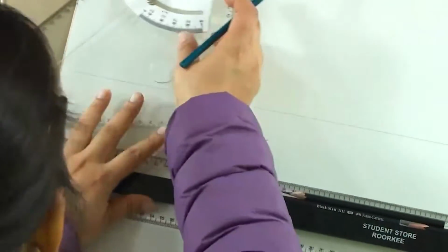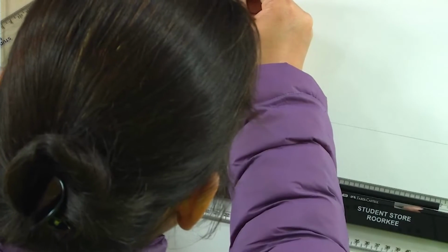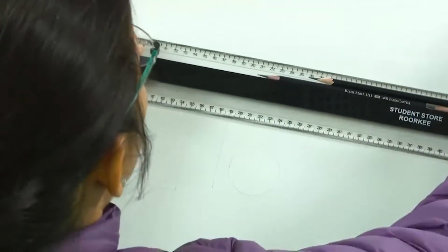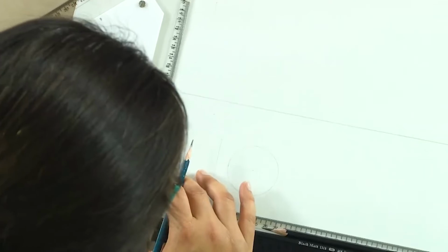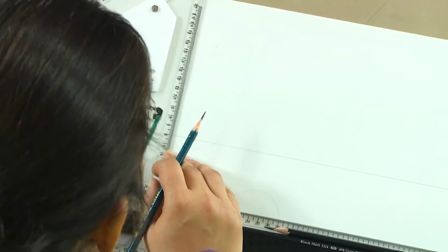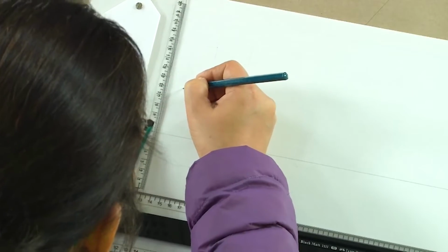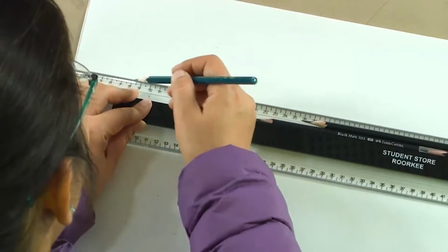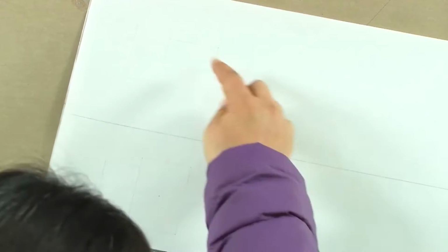So, assuming that the height of this prism is 10 centimeters. So, this is the height of the prism, and this is where your axis is coming. So, this is the place where the axis is coming. Now, this axis, we are assuming that it is cut in the center. So, this is the place where the axis is going to be cut. Now, because it is a circular cylinder, we will be seeing exactly the same profile here.